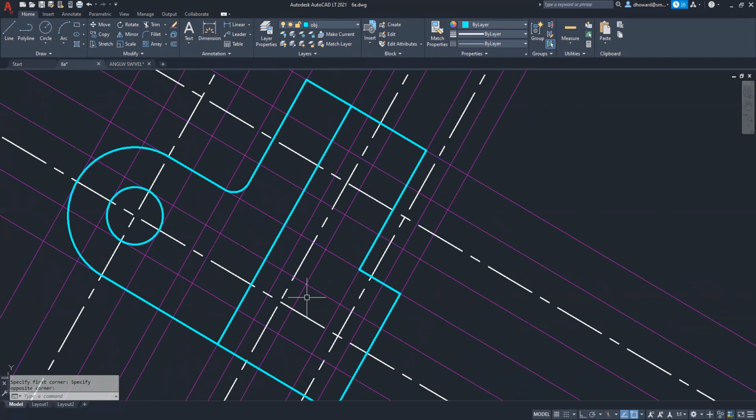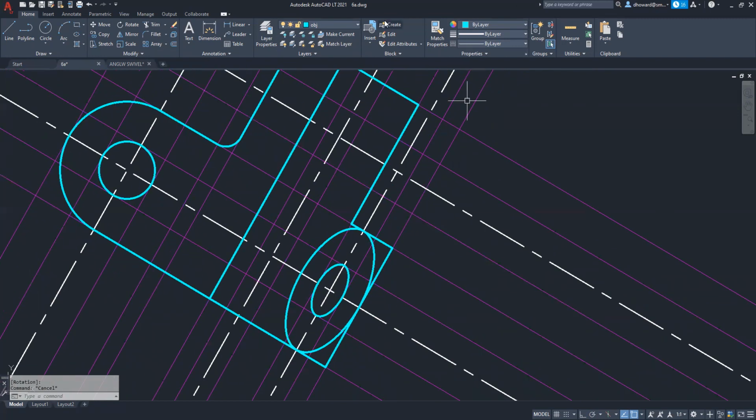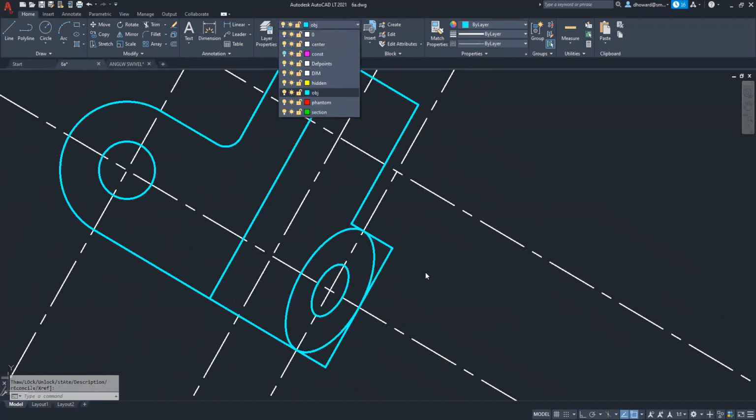Okay, so we know our ellipse hole is going to go, let's do the one on this side first. It's going to go within this rectangle here. We'll do that first. Go to my center ellipse and click on that center point, and then one edge and then the other edge. Boom. And then we'll do it again to do the outer here. So click on the center and go to the one edge and then to the other edge. There it is. Okay. And then I could turn off the construction lines and just trim accordingly.